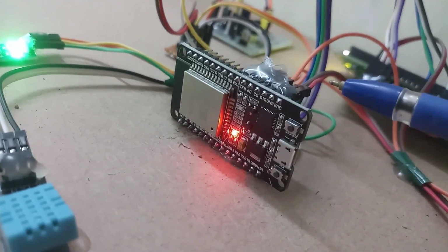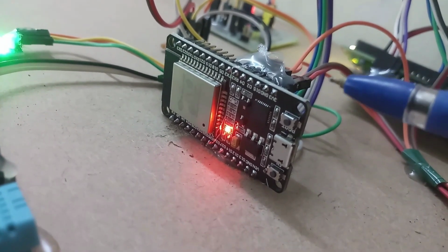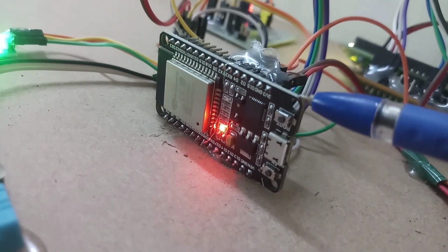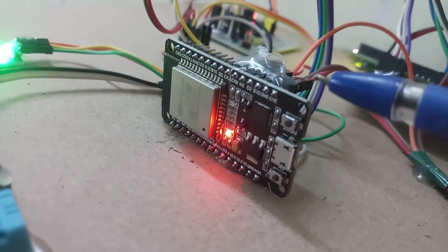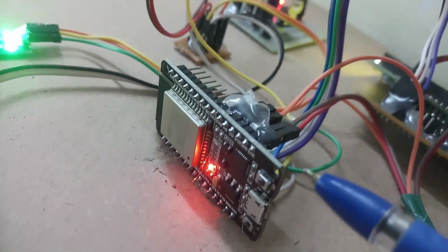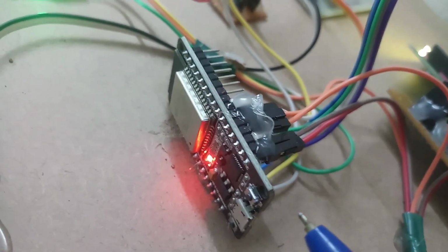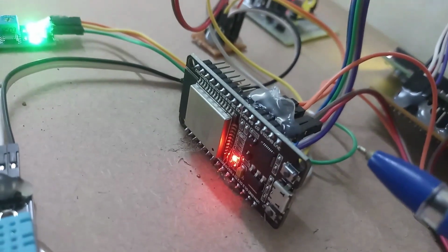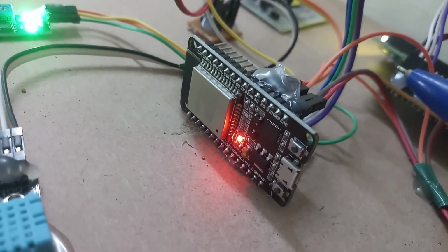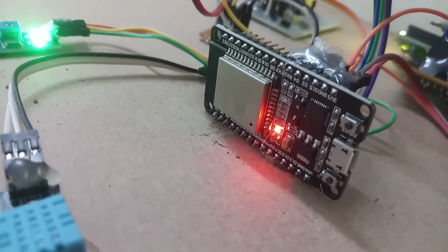The next component we are about to discuss is ESP32, which is the main component of this project. It has a Wi-Fi module, and this Wi-Fi module gets the data and transfers it to the cloud. ESP32 can perform as a complete standalone system or as a slave device to a host MCU, reducing communication stack overhead on the main application processor. It can interface with other systems to provide Wi-Fi and Bluetooth functionality through its SPI, SDIO, I2C or UART interfaces.